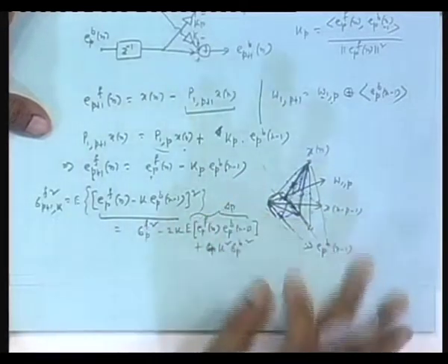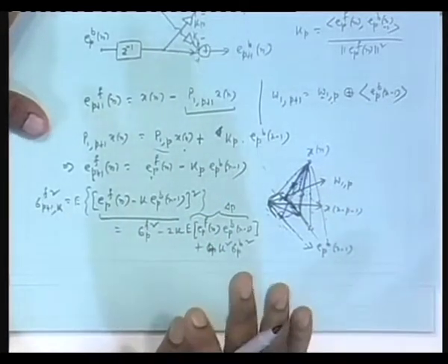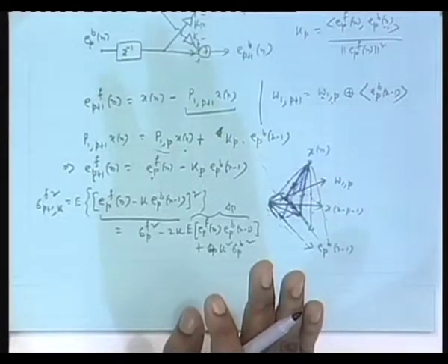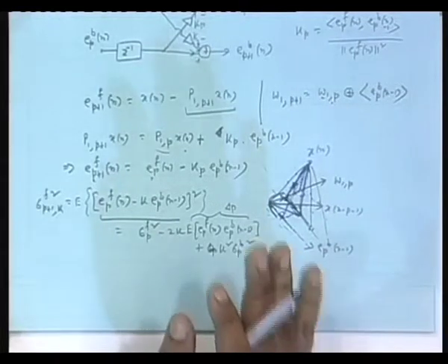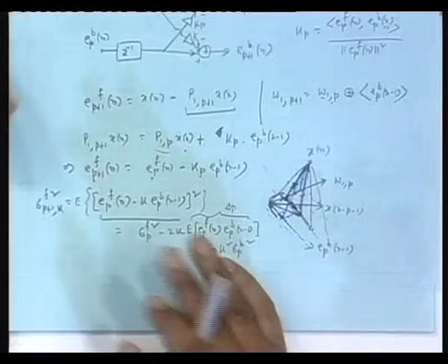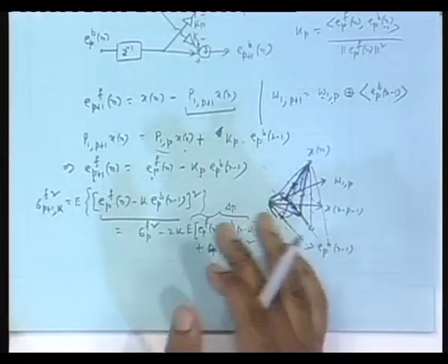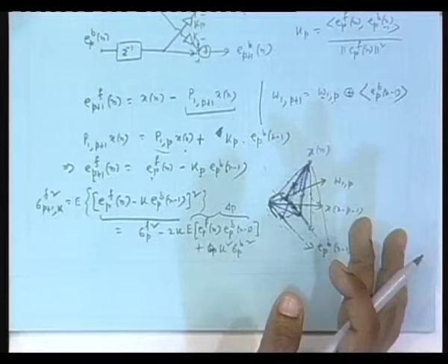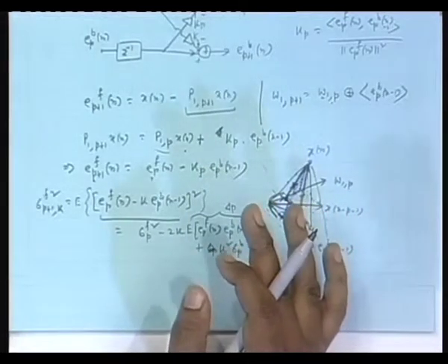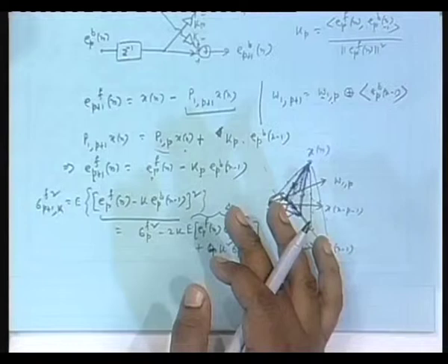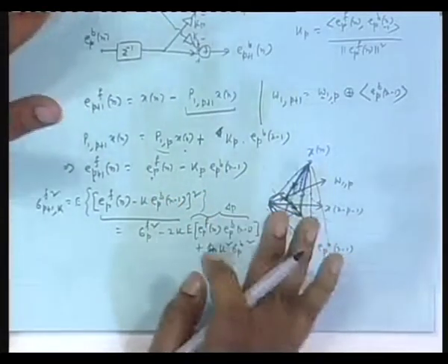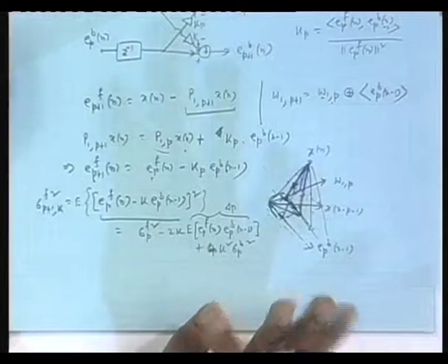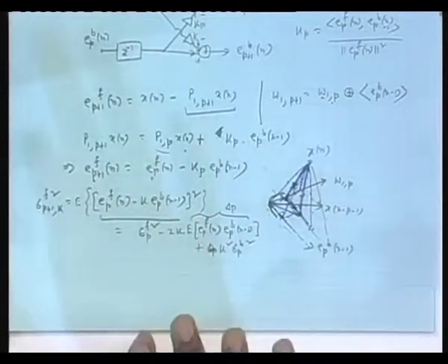I am assuming stationary process and all that for the time being, because when I moved to steepest descent from the optimal filter, I did not throw away stationarity, I assumed stationarity. That is, the gradient expression came there, R matrix was there, P was there. Afterwards, when I switched to LMS, I approximated R by a very wild approximation, xn vector into its transpose, no averaging and all that. P vector was approximated by xn vector into dn, no averaging. But that is only when I moved to LMS from there. Up to steepest descent, the stationarity assumption was valid and my gradient was in terms of R and P. Here also, when I go to steepest descent, the stationarity assumption will be kept intact.